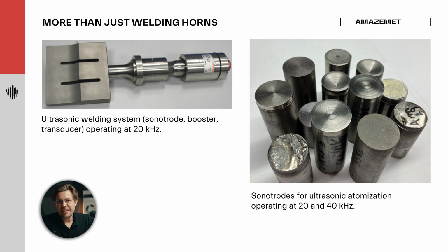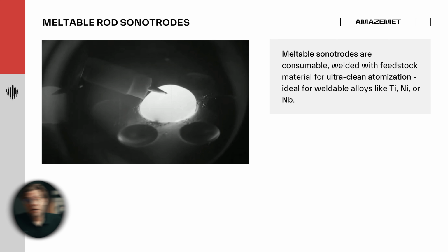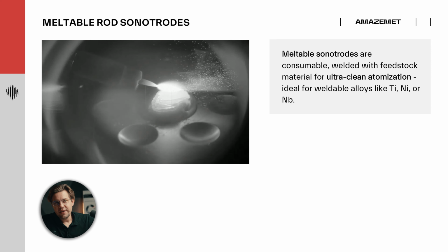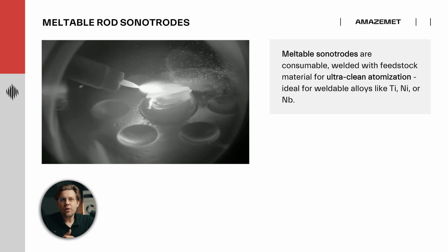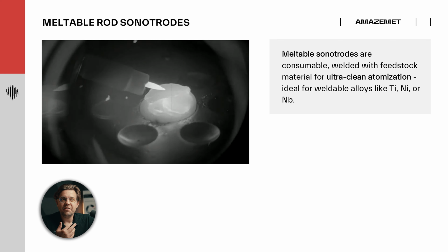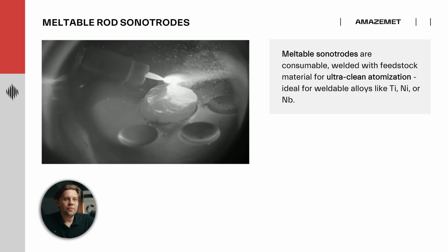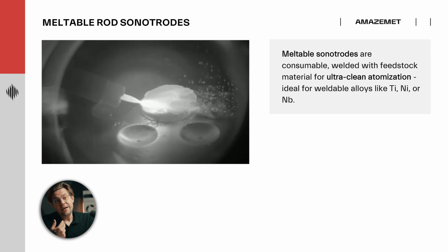People are using different names. You may know those as, for example, ultrasonic horns, ultrasonic probes, and many other names, but usually they are the very same elements. They are mechanical elements vibrating at a resonant frequency, capable of transferring mechanical vibration into the piece that we are actually processing. Mostly people use those for welding or cutting with ultrasounds. In our case, we are exposing those to elevated temperature, to molten metals, to provide spraying effect and ultrasonic atomization.